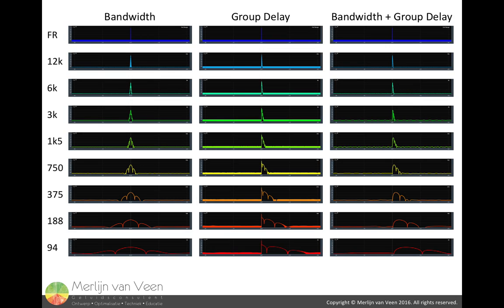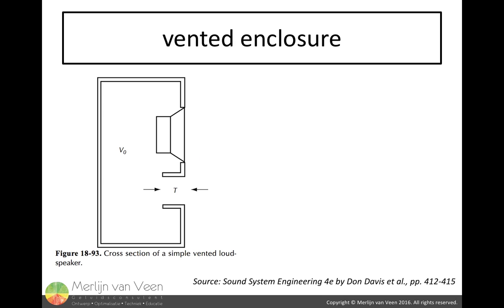Now that we understand how band limiting and phase shift together affect the impulse response, let's look at a virtual but typical subwoofer. The most common subwoofer design, arguably, is the vented or ported enclosure. Through the electrical-mechanical analogy, we can model the mechanical properties of the enclosure like mass, stiffness and friction in an electrical circuit made of resistors, inductors and capacitors.